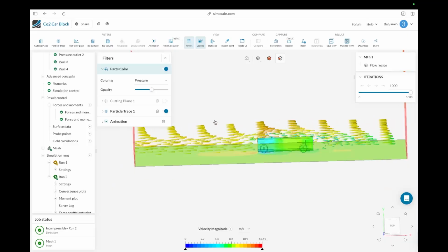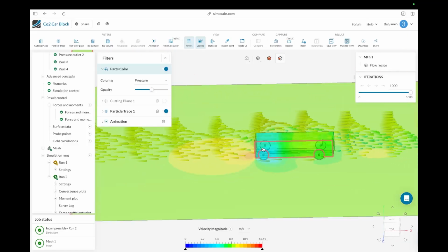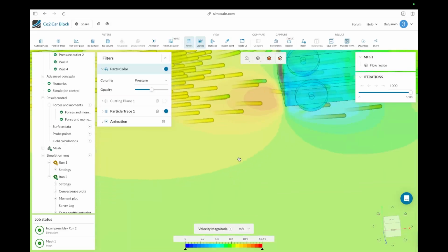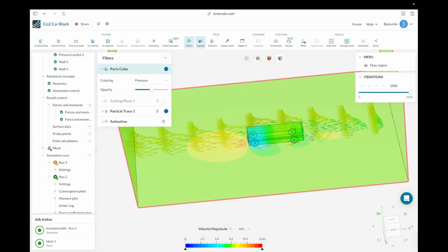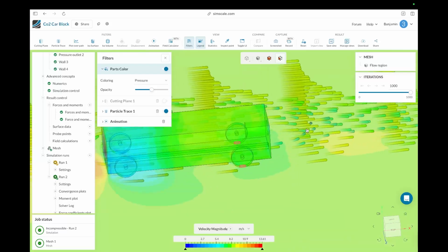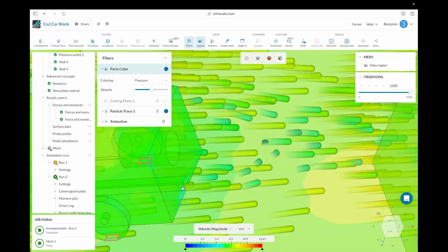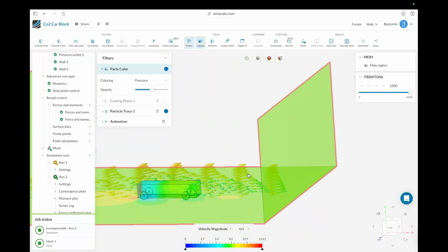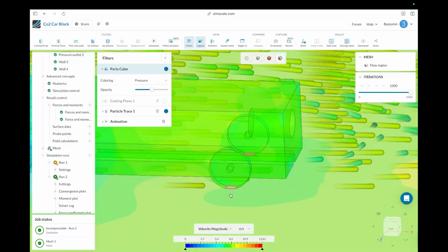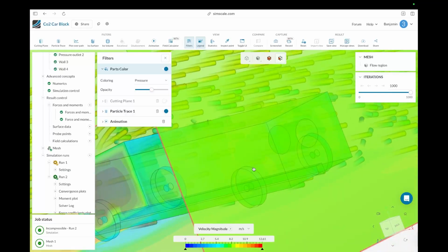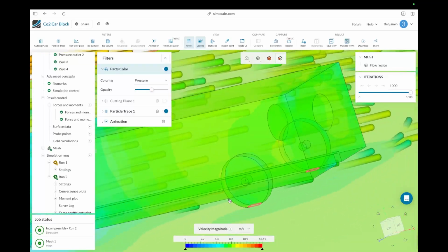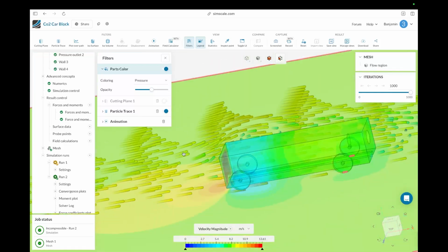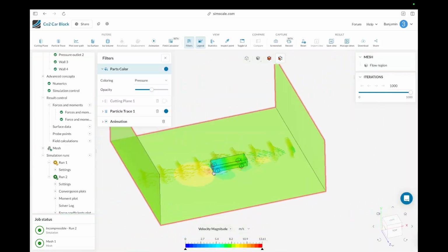So between a combination of these things, I think it's really clear to see how this flat surface at the front is pushing the air in a really weird way at the front, and then our big flat surface at the back is really sucking it backwards as well, with it not being very good behind here. Now, what's interesting is the wheels. You can't really see from either of our graphs how the wheels are acting. So that might be something we need to look at it in a different perspective.